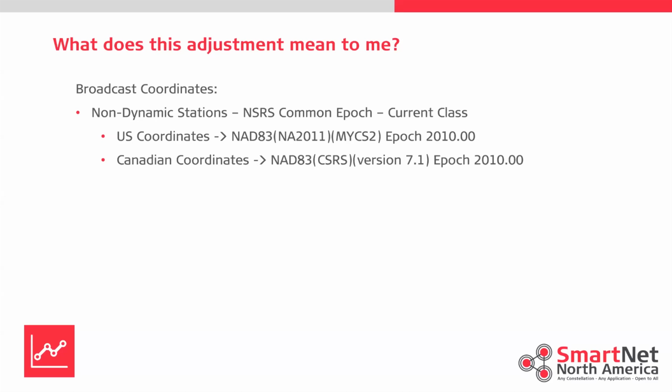So for a vast majority of our users, they're using non-dynamic stations. Okay, so they are going to get NAD83 NA 2011 with the new update MYCS2 and EPOCH 2010. And for the vast majority of our Canadian customers, they'll get NAD83 CSRS version 7.1 EPOCH 2010 on the standard mount points. So this is what you will be moving to.